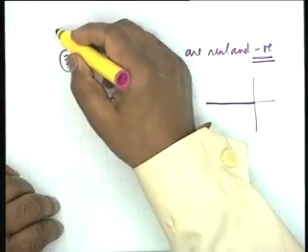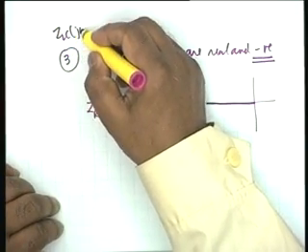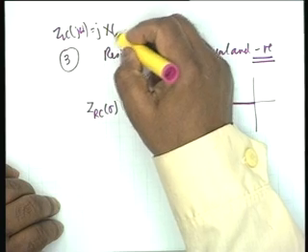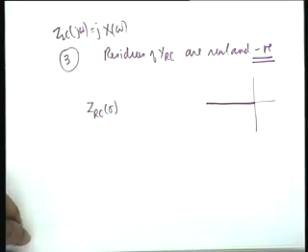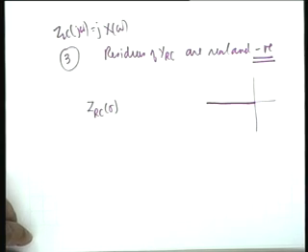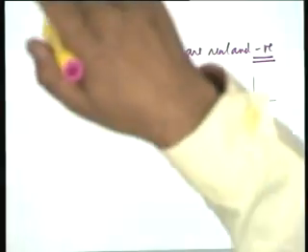So, what we did was we took a ZLC of j omega and put that equal to j X of omega. Capital X we called what? Reactance, not susceptance, reactance. And similarly, YLC we put S equal to j omega. Why S equal to j omega? Because the critical frequencies are on the j omega axis. And then we put that equal to j times B of omega, where B is susceptance.